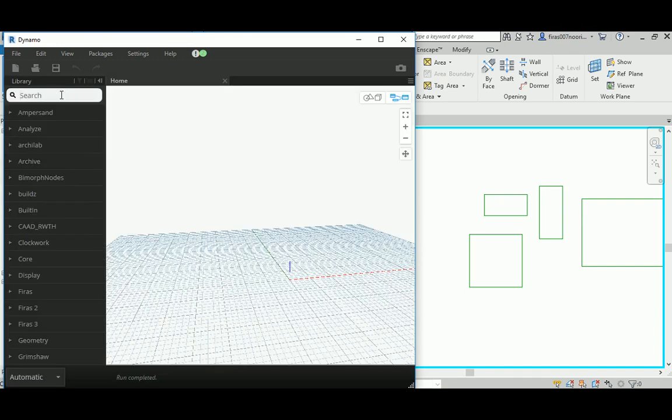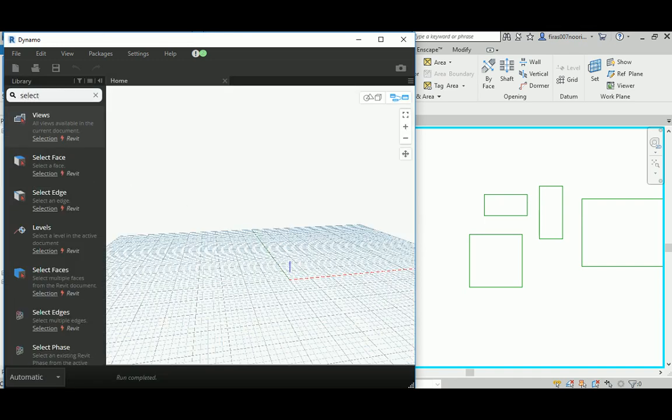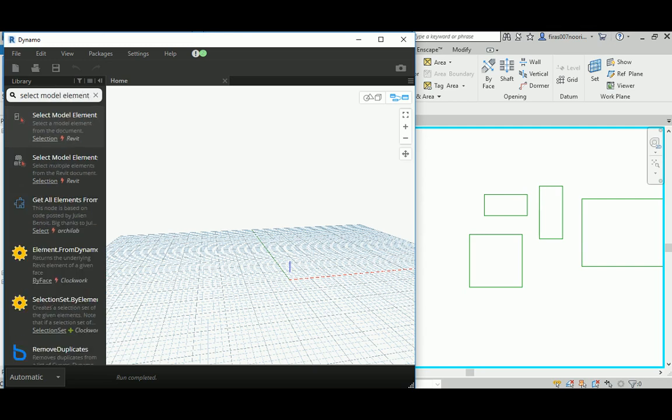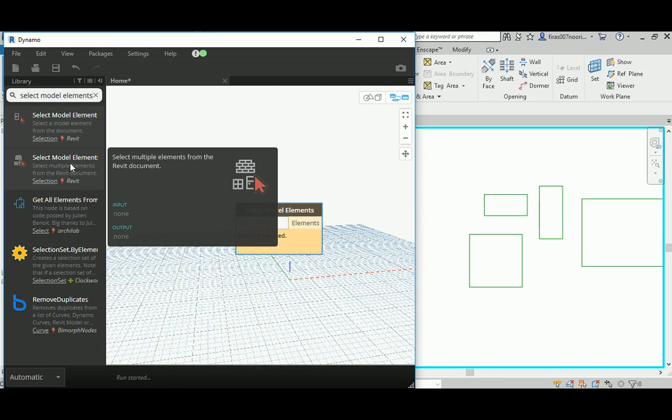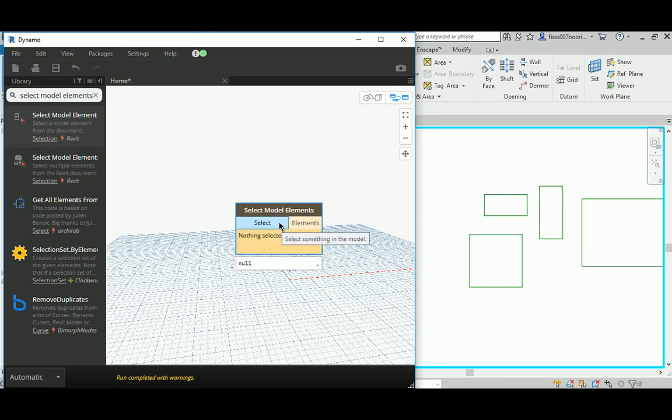And indeed, as we go, you can see that we need to select model elements, because I'm not creating the tower based on Dynamo elements, but rather on the existence of a group of model lines from the Revit space, as you can see here. I hid the elevations as they are really annoying when you select, and make sure you select model lines, sorry, instead of elements. So you have to select a group of lines in the same window.